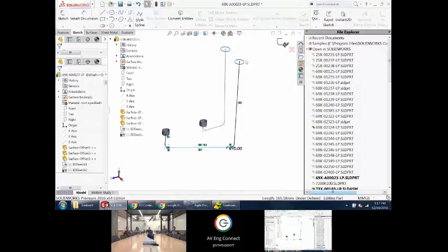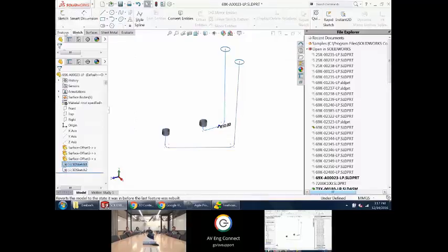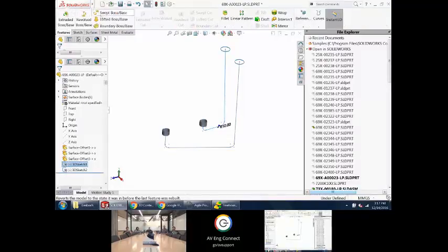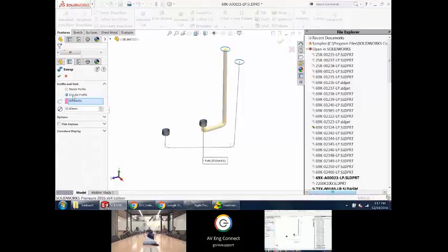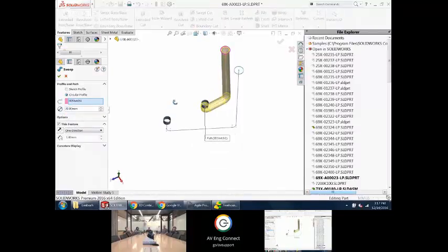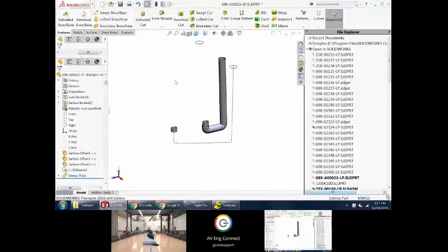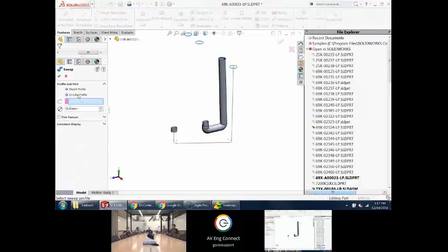I want to do them as 2 separate 3D sketches because you pick the sketch, you go to surface, you go to features, sweep. If you choose a circular profile, it just sweeps a circle down that path. You can even tell it to do it as a thin feature, so it can actually create a pipe for you. But this is the type of thing that you do for routing pipes, routing cables, that sort of thing, where you can grab the information from the assembly. If you have that break references on it, you're just stealing the information temporarily. The assembly could change, but typically if you've got an assembly changing that much, you're going to need to reroute all this stuff anyways.